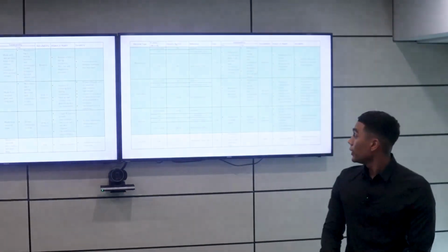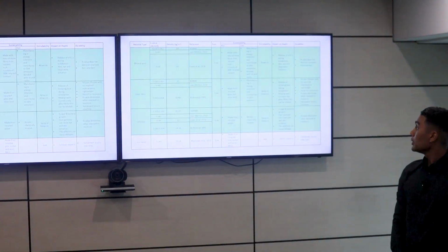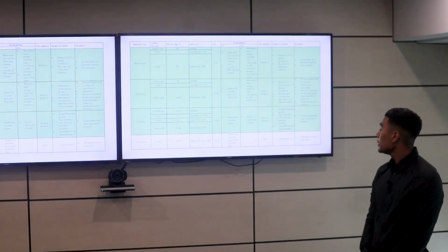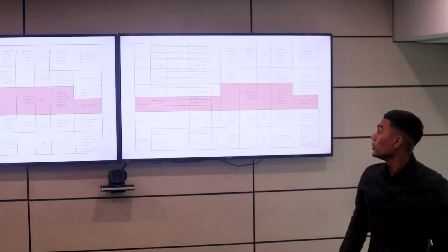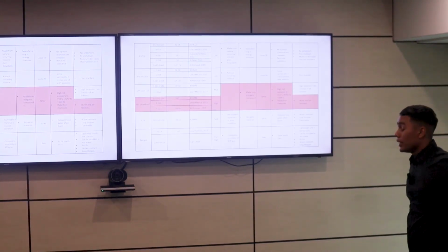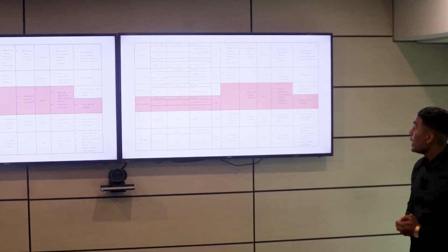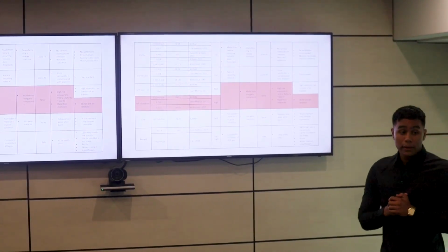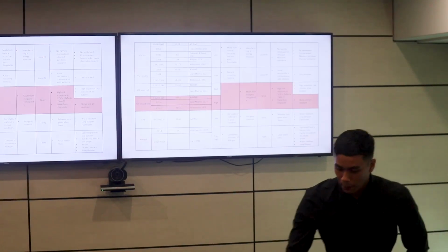I compiled the table summarizing all the different material characteristics of the candidate materials. The ones highlighted in green were used in the analysis. The table carries on to the next slide. As you can see, SPF closed cell is highlighted. This is because out of all the sprayable materials, SPF closed cell has the lowest thermal conductivity. Therefore, it was used to compare with the rest of the insulation materials.